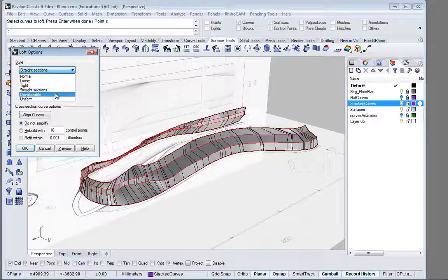It's very computationally intensive, and it oftentimes doesn't work on these super organic surfaces. So you'll get patches of it that are developable, and other spots it won't. So it will radically change your shape. So if you're going to try to build a developable surface, you want to start thinking about that beforehand.